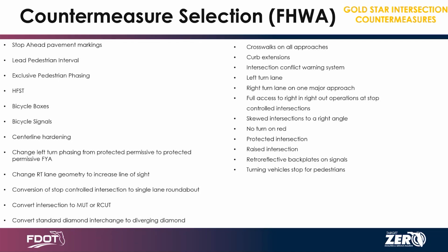Then you are tentatively multiplying the CMFs, the crash modification factors, not crash reduction factors, because that does not work. You're multiplying the CMFs with a maximum of 3. But if you remember also the new NCHRP that's coming out, it has recommended language for HSM2, that they're now saying just take the strongest CMF that you have and apply it by itself, regardless of how many countermeasures you're using.